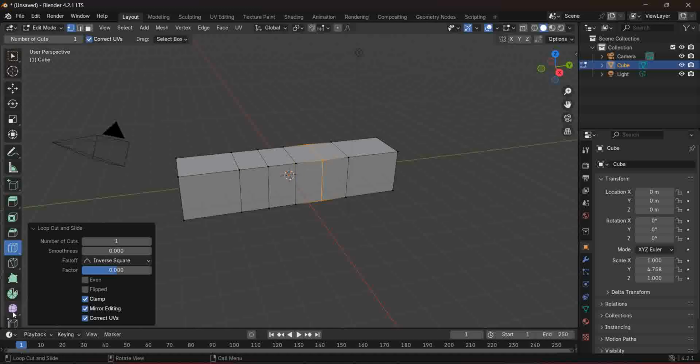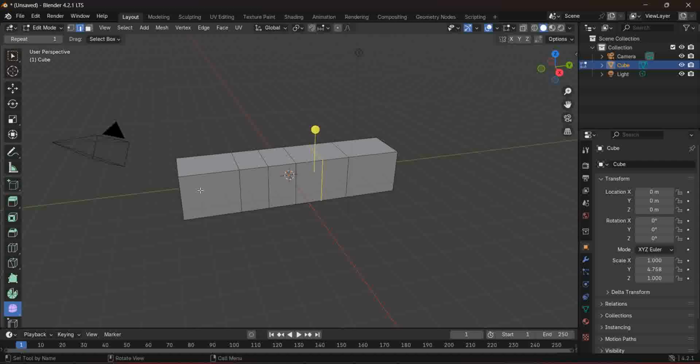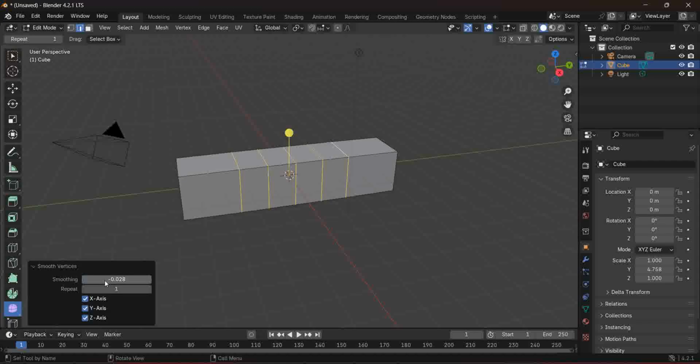Then I'm directly going to the smooth tool here. Now I will select all these things, but make sure you keep yourself in edge mode, and then select this with Shift and then Shift Alt N. Like that you can select the whole loop, the whole cut, and one more. Now let's click on smooth. As I'm clicking on smooth, you can see this yellow tower kind of thing. You just need to drag it and the window will open here. This window is responsible for playing with the smooth. So let's say I'm just smoothing my object.